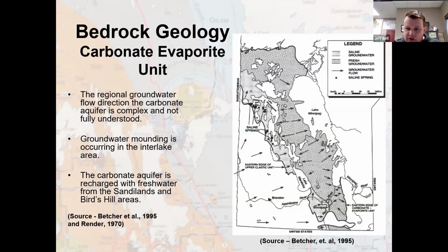As we go further towards the west, particularly through the middle of Winnipeg, the southwestern portions of Winnipeg and the western parts of the St. James area of Winnipeg, that's all naturally saline. And there's another saline-freshwater boundary that we have to contend with. Basically, in the Winnipeg area, it tends to follow the rivers, except in the St. James area, it kind of trails off towards Lake Winnipeg. In those areas, that's where the formation's naturally salty. And the change is a little bit more pronounced than what we see in the underlying Winnipeg Formation.